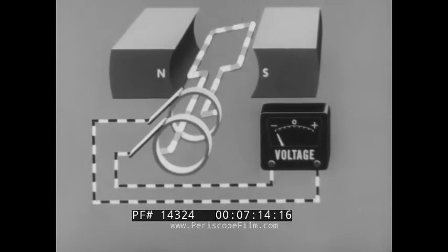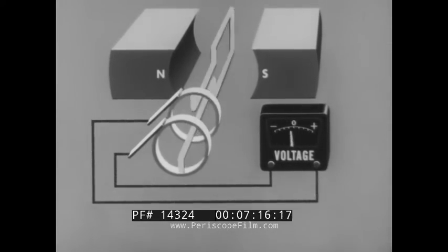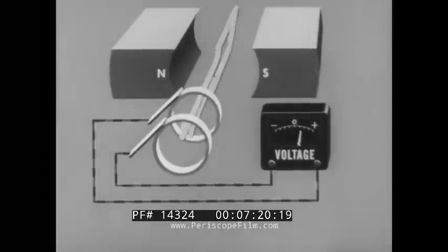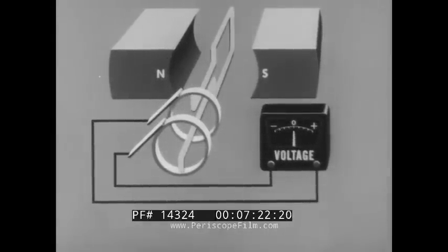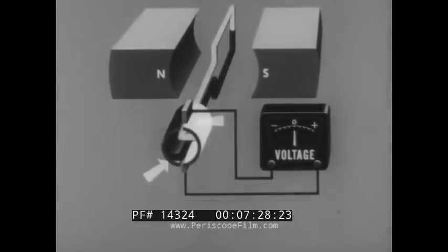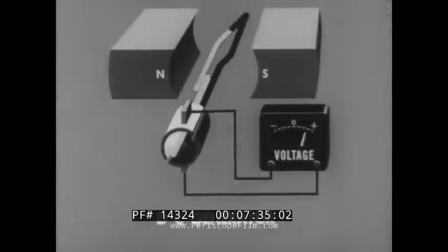What you have seen so far is really the theory and operation of a basic AC generator. But our purpose was to explain the principles of operation of a DC generator. To get direct current, we will attach each end of the conductor to a segment of copper, forming a commutator. Now our machine is a DC generator. The commutator rotates with the loop.